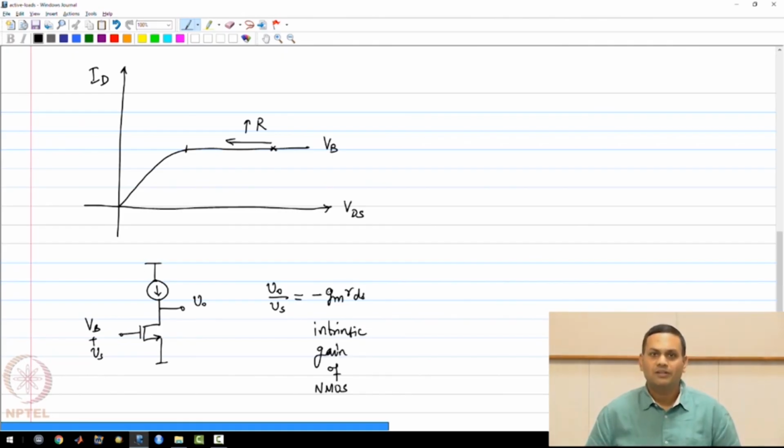So you may remember that this is the largest gain that you can get from a transistor. So what we want to achieve is a common source amplifier which has a gain that is as close to this as possible. This of course does not have strong limitations on output bias point, because the current source can have a large range of voltages across it without changing the current.